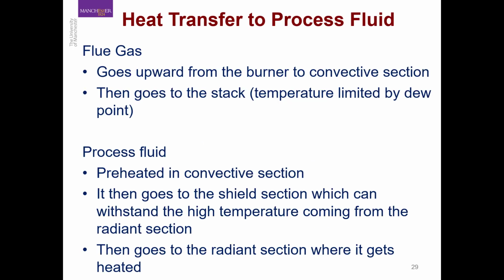As I said previously, the heat that is generated by the fuel will be transferred to the process fluid. The heat will come from the burning of the fuel to get the flame, which will then radiate heat and also produce flue gas. That flue gas moves upward by either natural convection or forced convection, depending on what kind of drafting mechanism you are using. Then it exchanges heat with the convective section and goes out of the stack, and the temperature at which it goes out is normally decided by either the pinch temperature, the dew point, or the shape of the GCC.